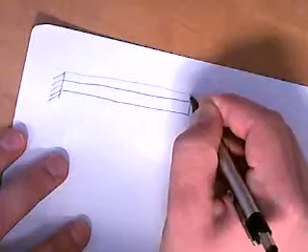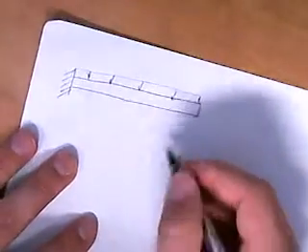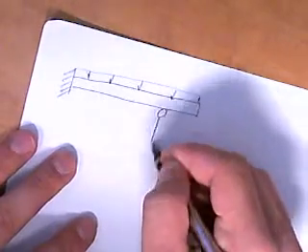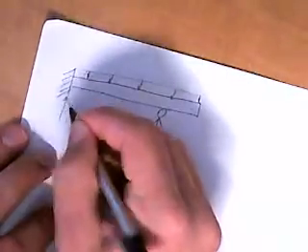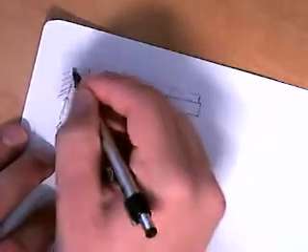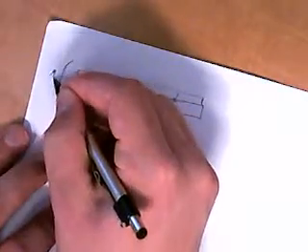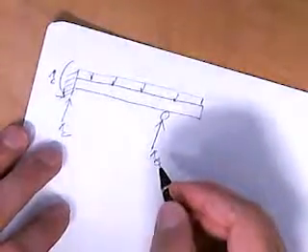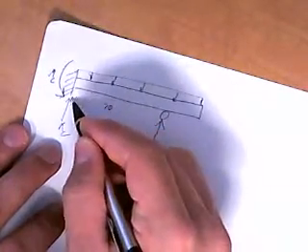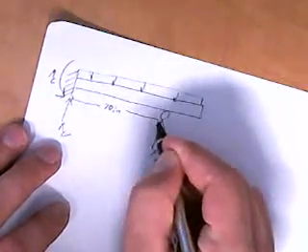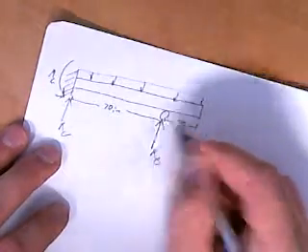Okay, so we've got this thing going on like this, a distributed load, and then we also have this spot right here with a reaction. We're going to call it RB. And we've got a reaction back here of RC, and then a moment, which I'm going to call MC, and that's about it. We know that the distance is 70 inches in here, 70 inches right there, and then 30 inches right here, just like that.